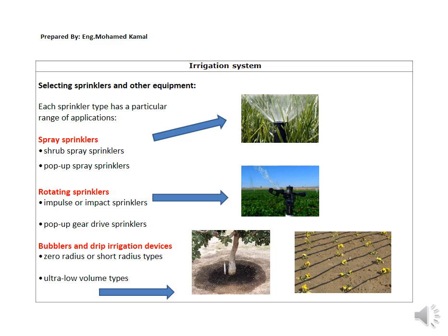So there is no chance of mis-irrigation or losing water through splash outside the green area. Even the quantity of vaporized water from this system is lower than the rotating type sprinkler or the spray sprinkler. So this system is commonly selected when we are going to provide a water saving study through the system.